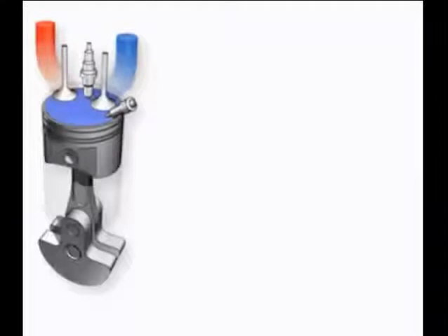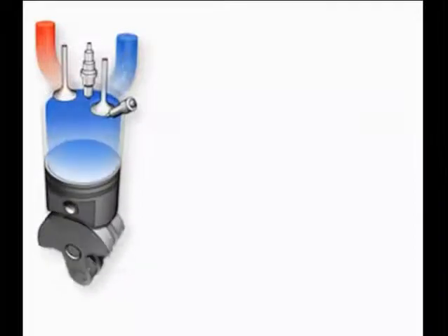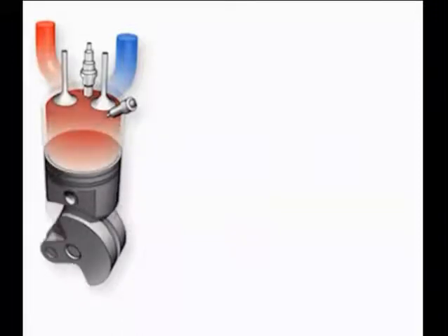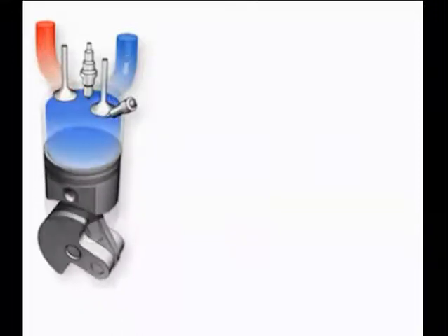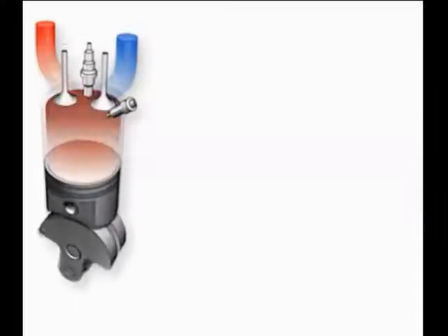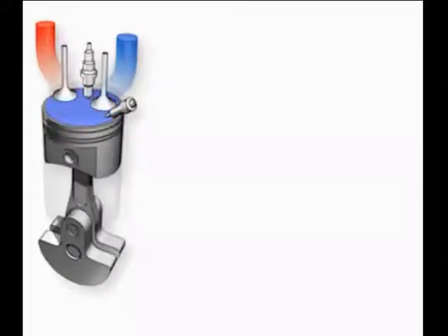Increasing efficiency. In principle, there are three options for boosting the output of an engine. Firstly, the displacement of the engine can be increased. Secondly, the speed of rotation can be increased. The third option available is what is called charging of the engine. We wish to briefly present the three principles below.